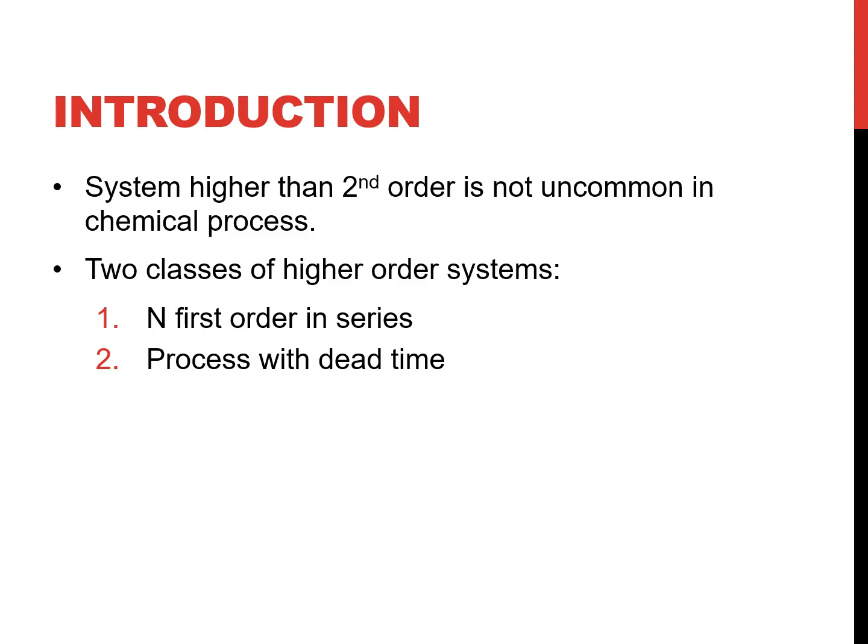Dead time means you have a time delay. Of course, usually if we take the reading from the unit operation, the reading is not spontaneous. For example, if you want to take the temperature at the distillation column, usually the reading is connected by electrical instrumentation. For temperature reading, usually we use a thermocouple. This thermocouple is connected to the distillation column.